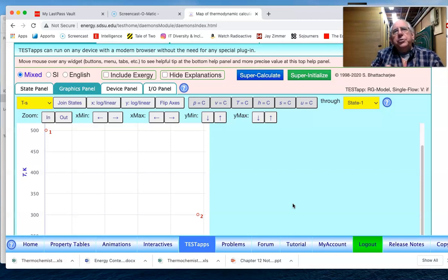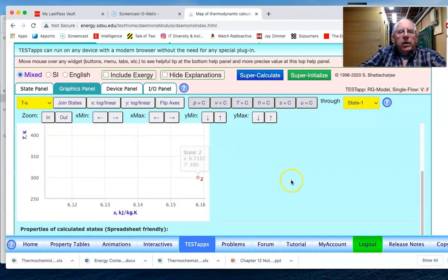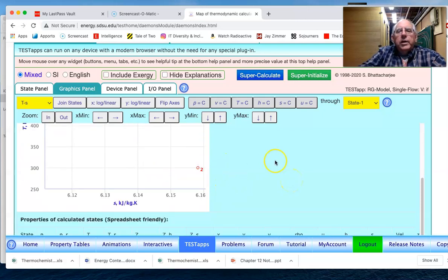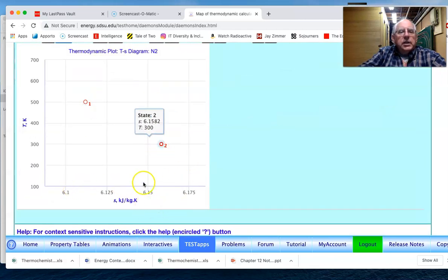And again, it's due to the conditions associated with the turbine expansion, and it's also affected by either heat transfer in or heat transfer out. And so this is the TS diagram. Again, if one wanted to, one could have changed the scale down here by zooming out a little bit. By zooming out, you can now see the two entropy values and the temperature process. And so, again, it's not an isentropic process, but rather one in which entropy has been generated.